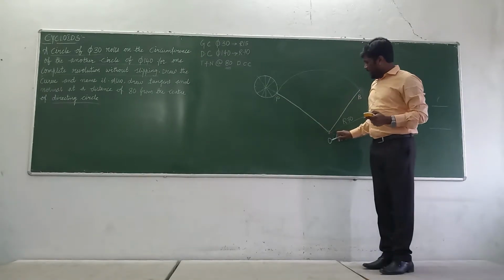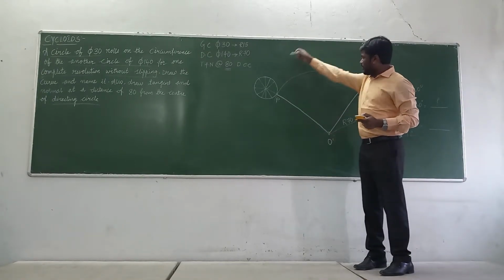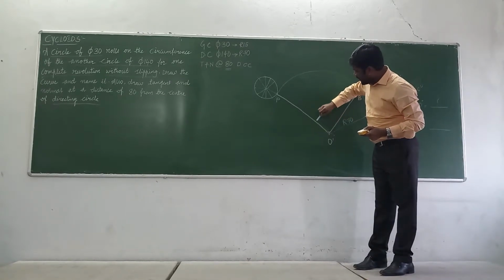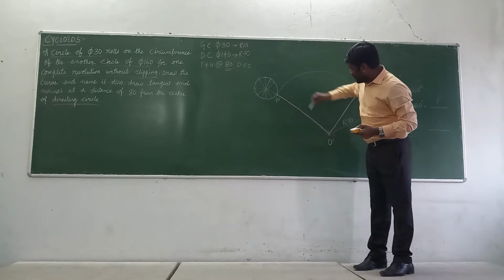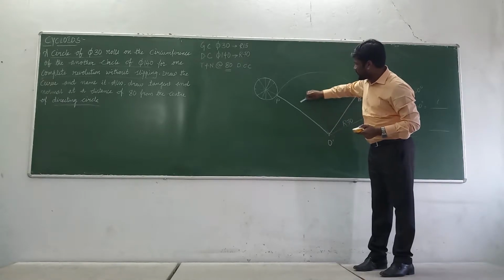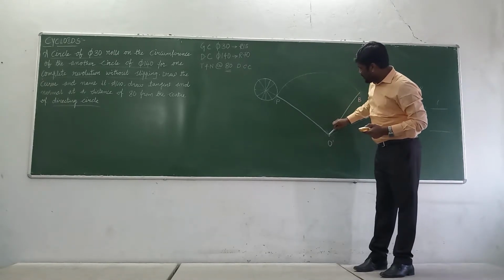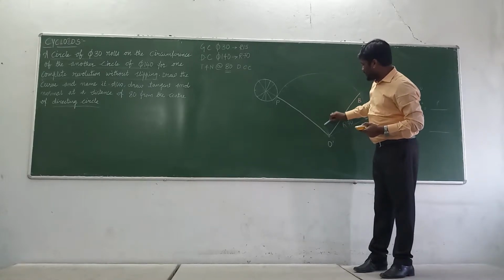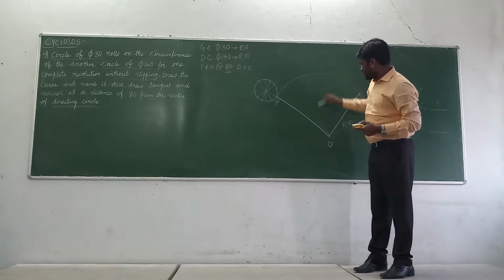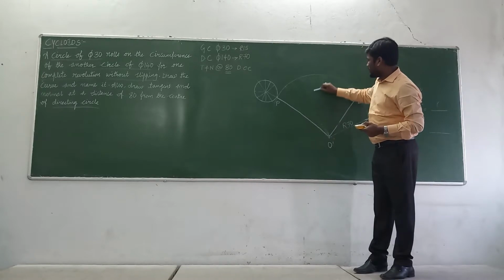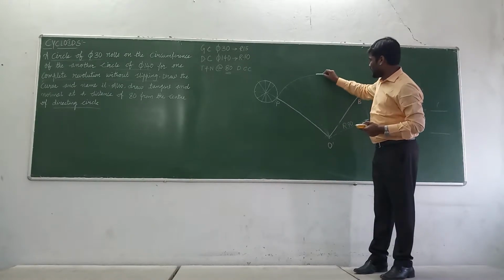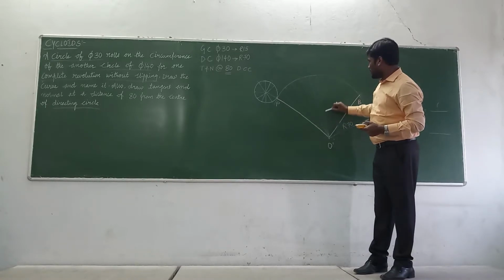Now from O dash, project all this onto the PB line. We are going to draw thin lines which will be equidistant when you work with the instruments after dividing. When you do it exactly with the help of instruments, you will get equidistance. As I am not using instruments, my drawings are not to scale.